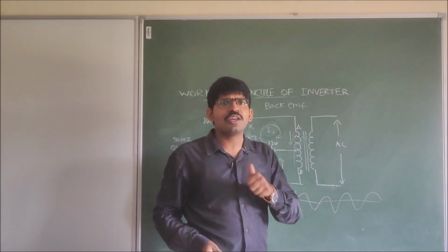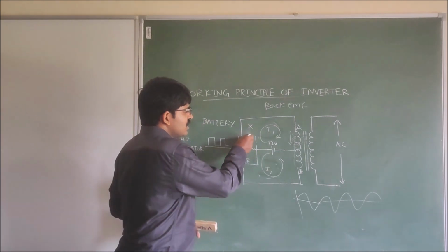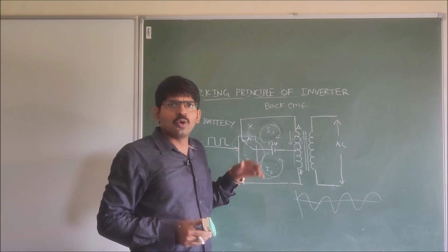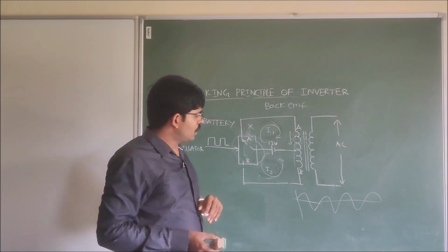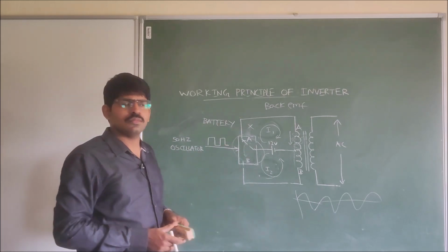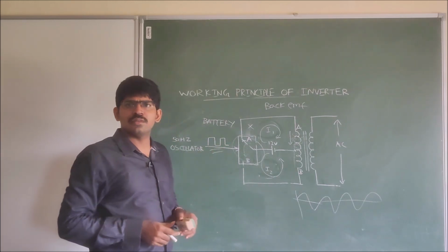Who is deciding this 50 Hz frequency? This switch is deciding the 50 Hz frequency. Who is controlling this switch? We are using an oscillator to control this switch. A square wave oscillator.